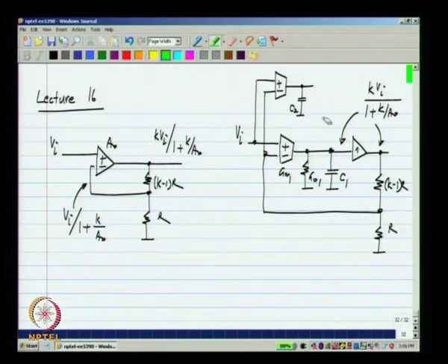So, I take this voltage and convert it to a current using another transconductor. Okay. So, this is all I have. Essentially, the block above is taking the difference between these two, integrating it, converting the integral to a current and feeding it into this. If everything works perfectly, then the difference between these two voltages has to be 0 in steady state.